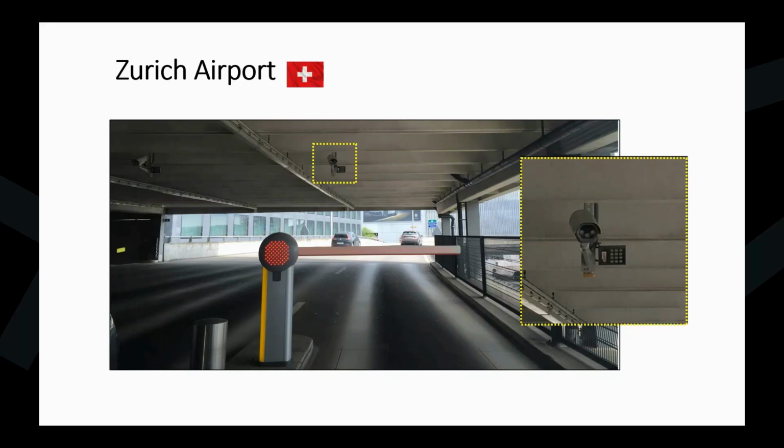However, I kind of wanted to use this as a starting point because this is, dare I say, the easiest setup to achieve good results. You know, it's close to the entrance, narrow field of view, camera and lighting mounted very closely together. There are some things that they could have tweaked, so they could have maybe had the lighting closer to the vehicle, for example, so that it's going to bounce off the plate from a closer range, and therefore more light will reflect back into the camera.